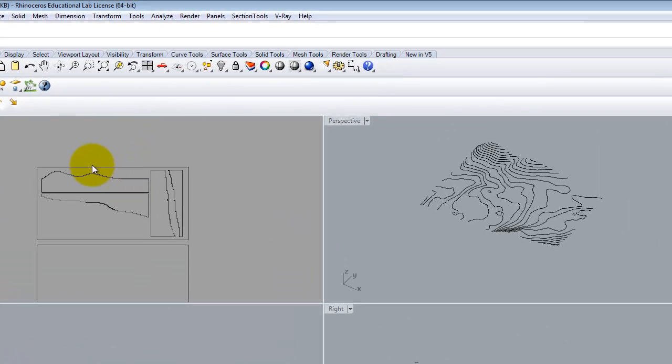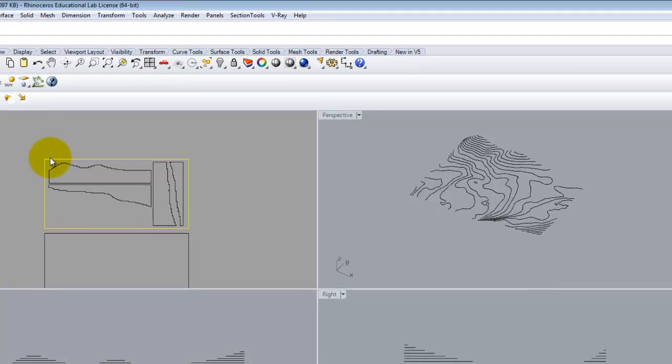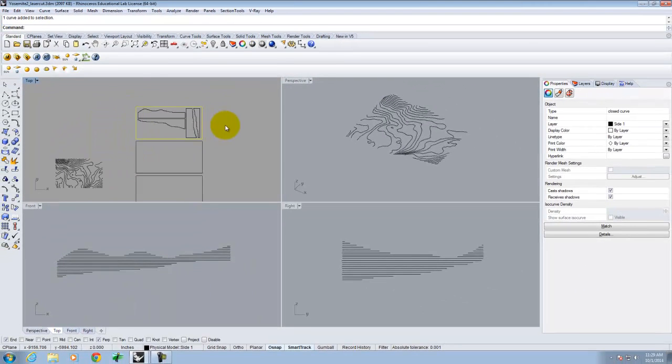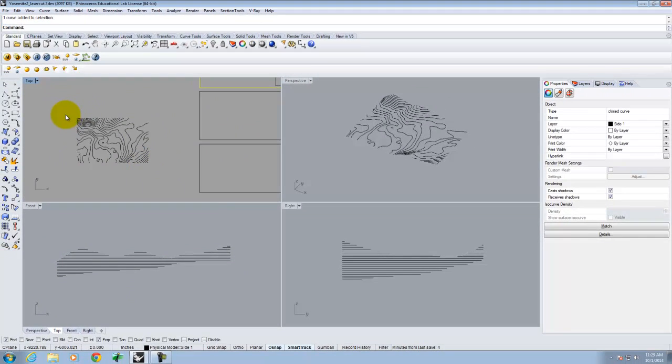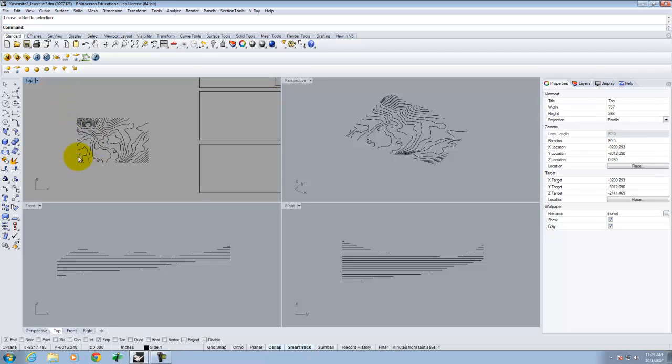of cardboard. This outer rectangle represents the overall cutter size. The laser cutter can't cut all the way to the edge. It leaves maybe an 1/8 to a 1/4 inch around the sides, so you can't do a full cut. It's got to be slightly smaller. But that's already laying out my first board. Okay? Now, when I get here, I have my topo lines, and this is where the tricky part comes in.